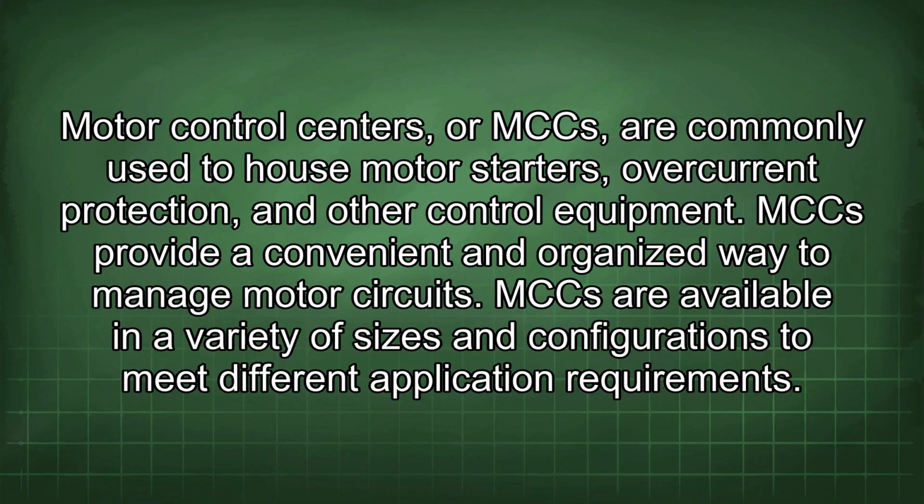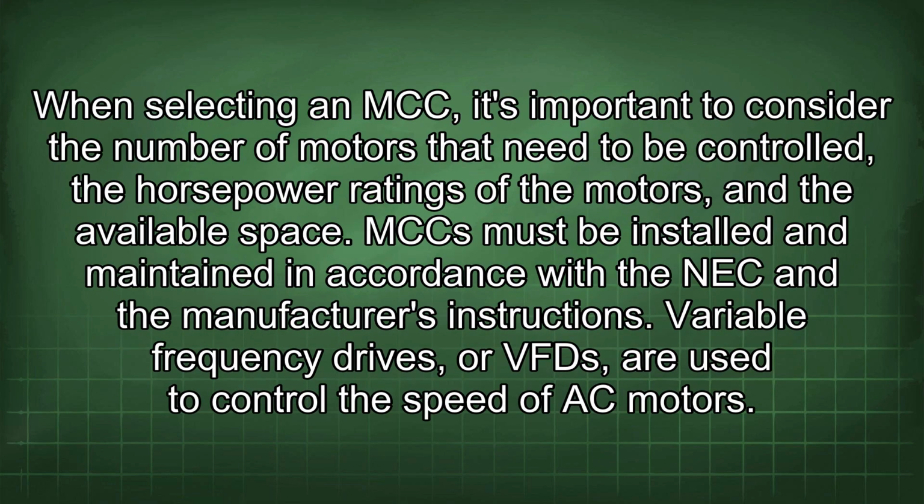Motor control centers, or MCCs, are commonly used to house motor starters, overcurrent protection, and other control equipment. MCCs provide a convenient and organized way to manage motor circuits. MCCs are available in a variety of sizes and configurations to meet different application requirements. When selecting an MCC, it's important to consider the number of motors that need to be controlled, the horsepower ratings of the motors, and the available space. MCCs must be installed and maintained in accordance with the NEC and the manufacturer's instructions.